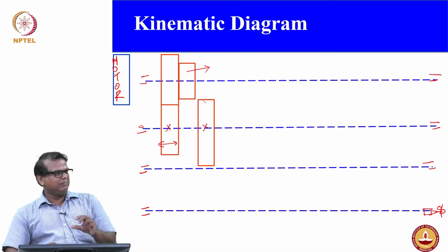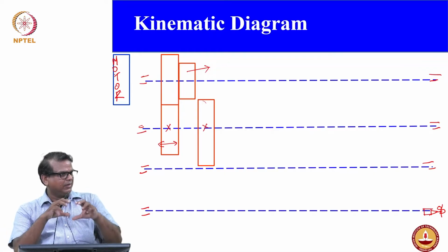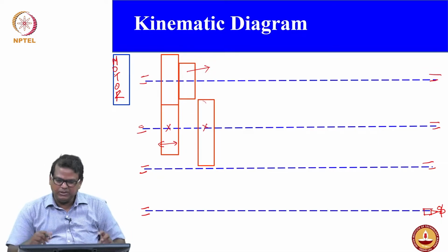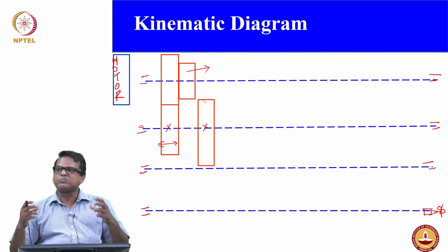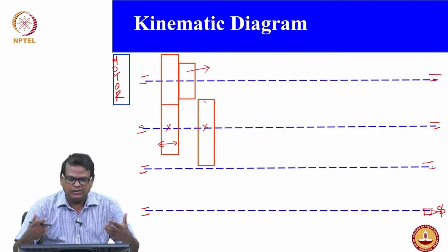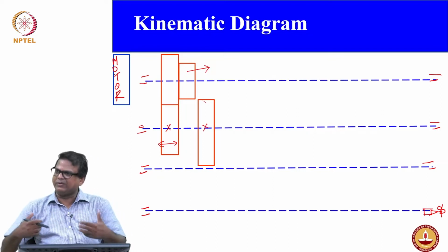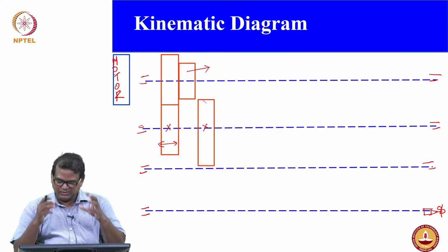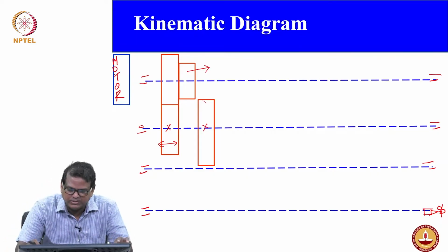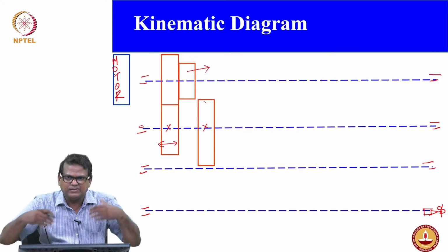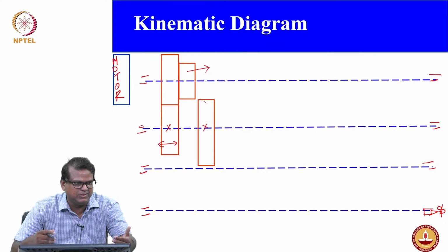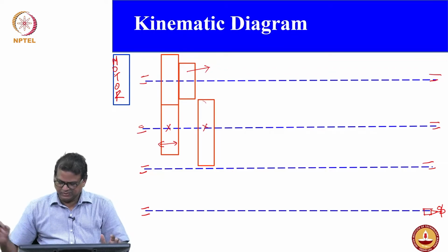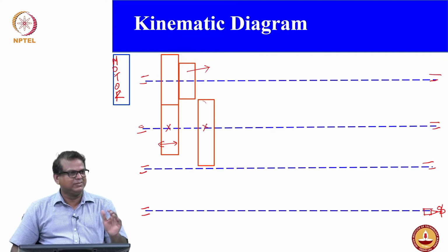Please understand that the spindles should keep the same center distance between two shafts. Between two spindles, the center distance must be constant. Of course, the same center distance can be kept for other stages also, or you can have different ones, but as long as the shafts are placed, one spindle should maintain the same center distance to the previous stage. That you have to follow. Now it's okay, right? We have done the first stage.